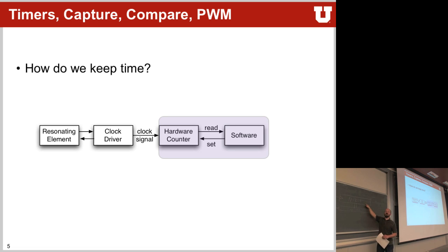If you ever designed a counter, it is not instantaneous. If you looked at the ModelSim simulation of your counter, you see that the bits change at different intervals of time. So if this signal comes in while this is just incrementing, then your capture value will be garbage, right? So oftentimes your captures actually have logic in them to synchronize to this clock up here.